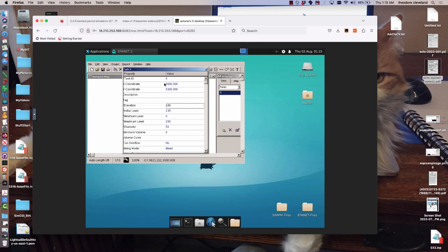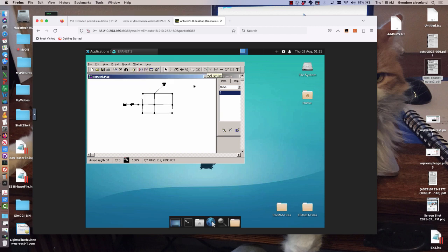If the network needs water from the tank, it's going to come in initially at this head, and then the tank water level will drop. And so then the head will be reduced, it'll drop some more, and the head will be reduced, and so on. And the computer program will track that once we turn on the extended period simulation.